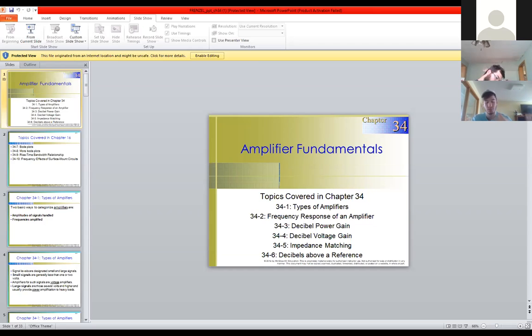We're not trying to be engineers here, but if we look at the amplifiers, of course, your signal levels, you either have small or large signals. And like it says here, small signals are generally less than 1 or 2 volts. And I will say this, for amplifiers, you do want to go through more with small signals, because if you go with a large signal on an amplifier and you try to amplify that, you're actually looking to cause more distortion, which is something we try to avoid.